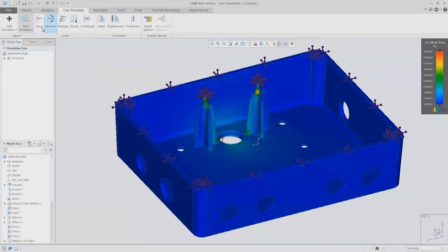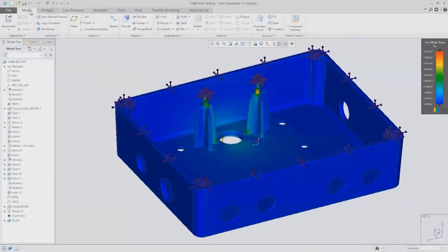The load is off the front face of that, and it's onto those bosses. Now it's up to me as a designer to determine, okay, is that acceptable? Is it still going to break on those bosses? The stress is still maybe outside of an acceptable range, but it's away from where we had it originally. But that's really the job as the designer, to be able to go through that, get the impact of those changes right in front of me.